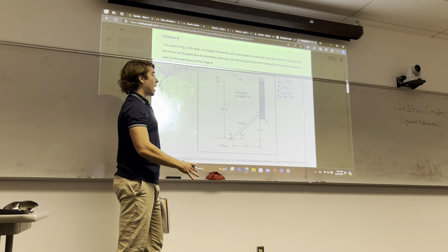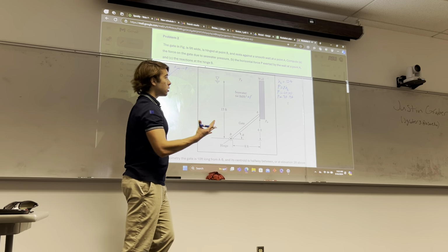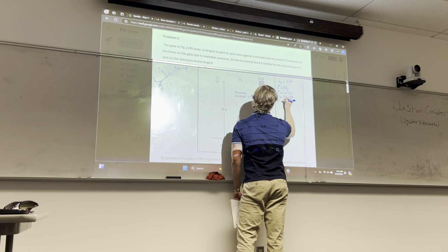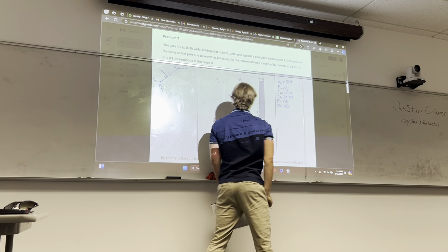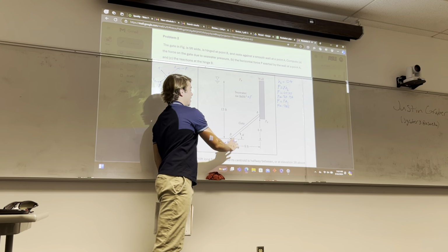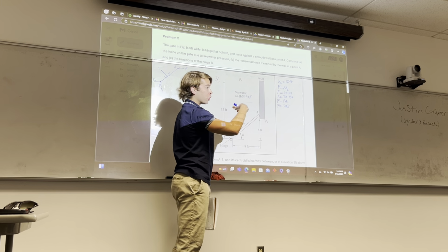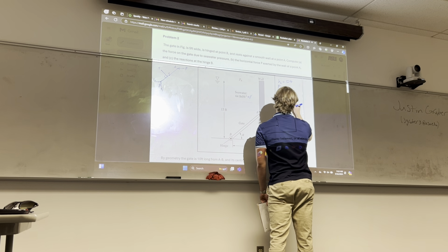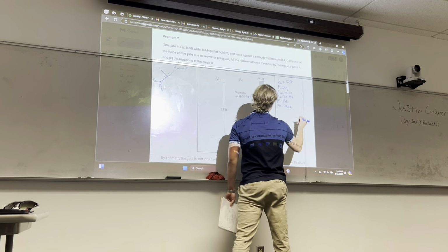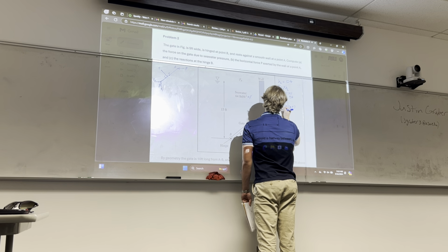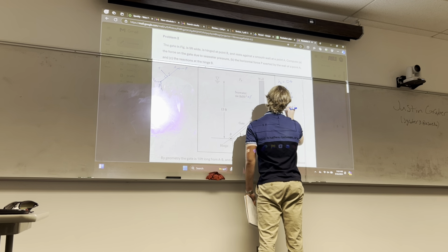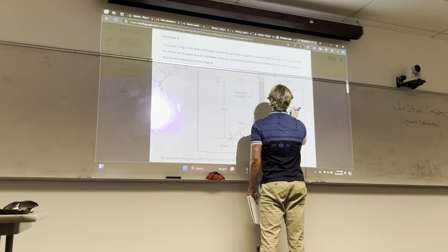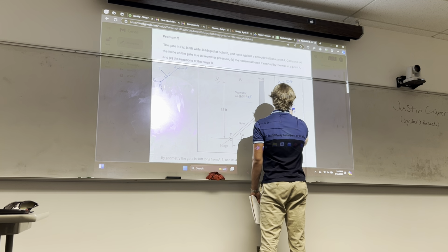So now to find the force acting on the gate, you just multiply it by the area of the gate. So F equals P times A. F in this case equals 768. And I'll just tell you, if you don't believe me, go do the Pythagorean theorem. This is 10 feet. 64 plus 36 is 100, square root is 10. We have 10 times 5 wide into the page. So the force on the gate itself is 38,400 pounds. All right, so there's part A done.